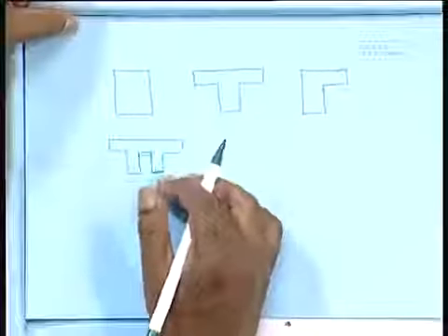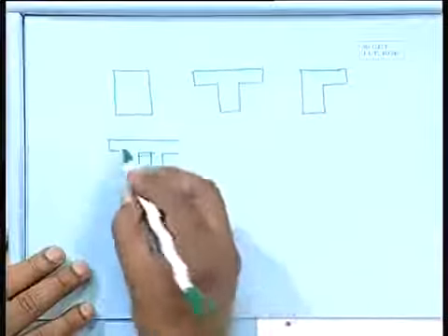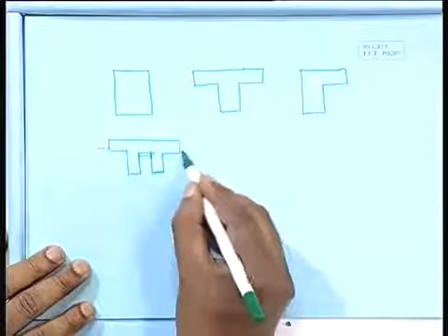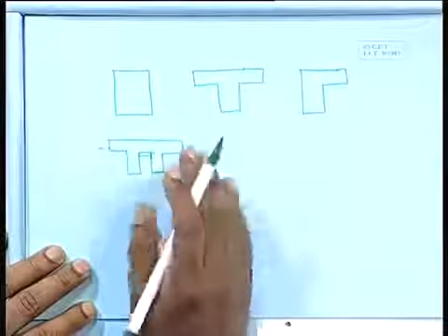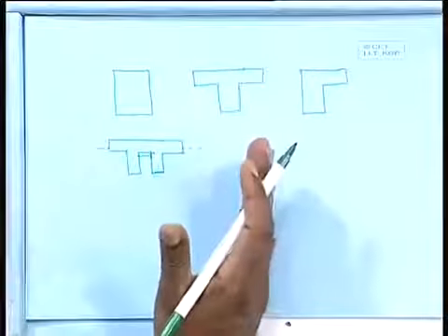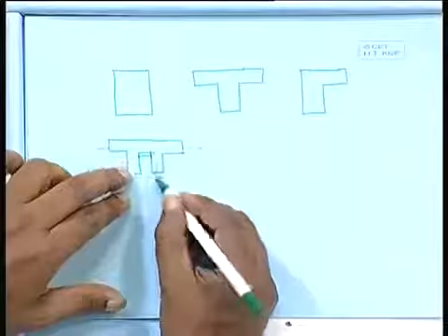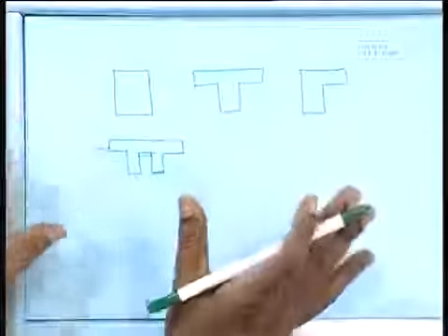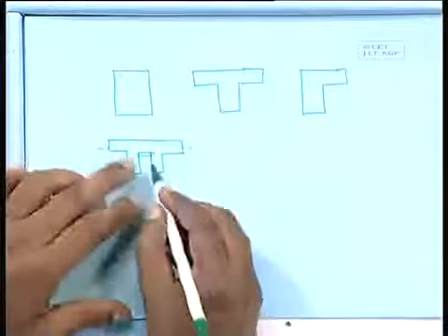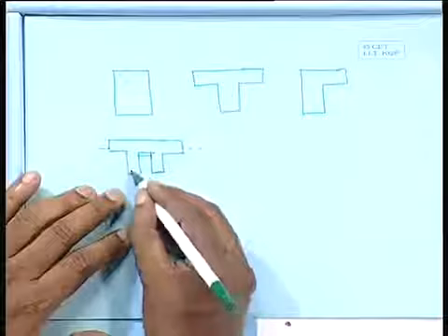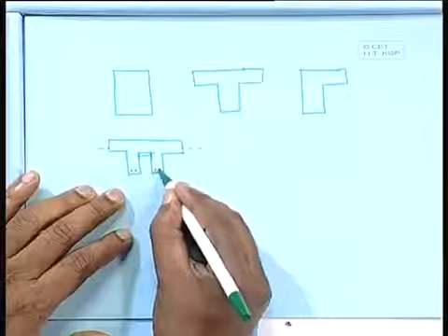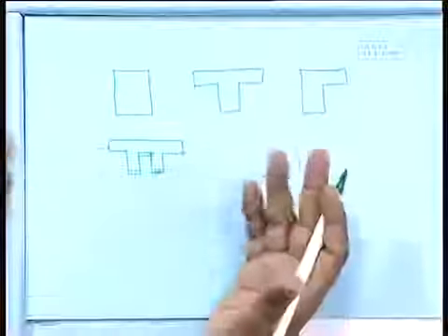Here again it is nothing but the T section. If the neutral axis can be provided within the flange, then there is no problem, because then it is a simple rectangular section, and the other part of the concrete is not taking any load or moment. Whatever reinforcement you provide here is the area of steel.